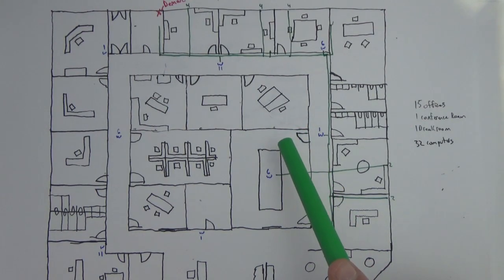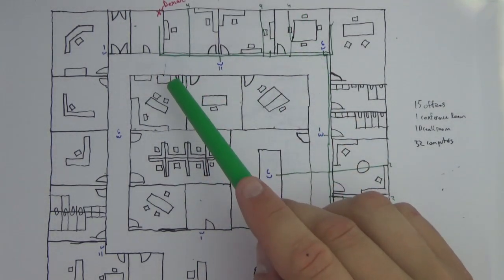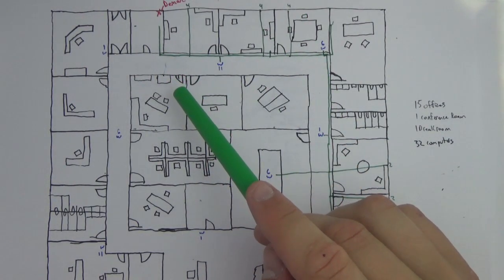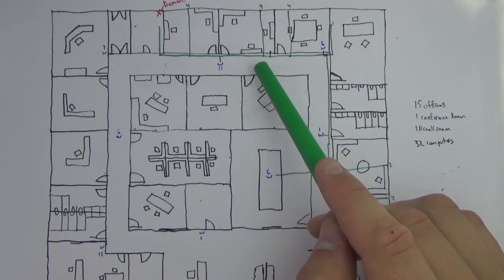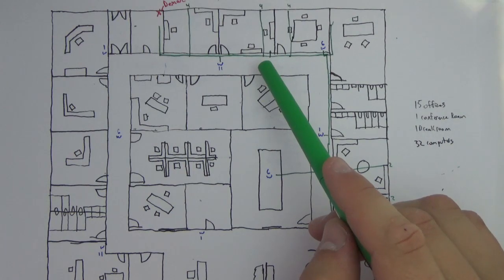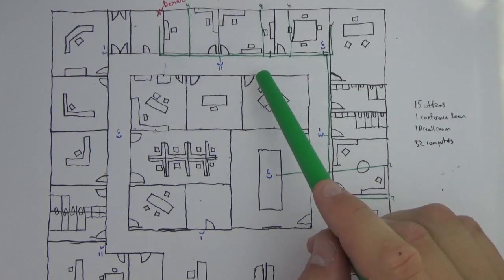We're going to make sure that all of the wires have continuity between both locations and that they're punched down in the right order. It's a frequent mistake to get two wires switched around, and so you'll be looking at your tester and it'll have two wires that are crossed. We'll need to repunch those down, or you'll have a wire that's broken.